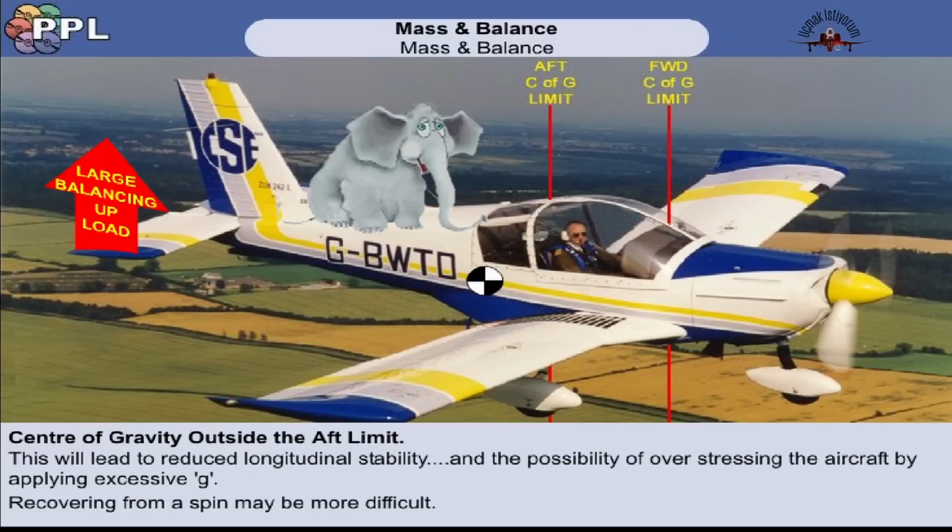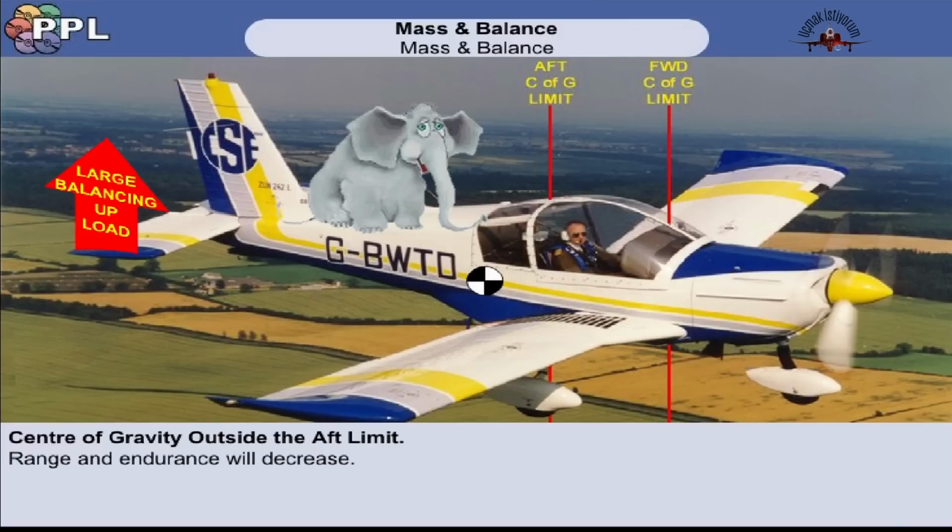Recovering from a spin may be more difficult because a flat spin may develop. Range and endurance will usually decrease due to the extra drag. Glide angle will be more difficult to sustain because of the tendency for the aircraft to pitch up.